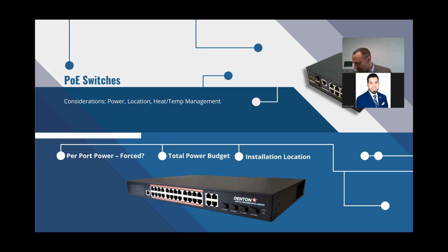The other alternative that you could do is, and by the way, this guy does need to have good ventilation. With these higher powered PoE switches, you don't want to bury them in a hot box because they are handling a lot of power. So good ventilation is important. We do specify in our documents what wattage you get out of this guy in terms of heat rise. You need to make sure you note that, and that is actually one of the requirements you present. We'll talk about that a little bit later.